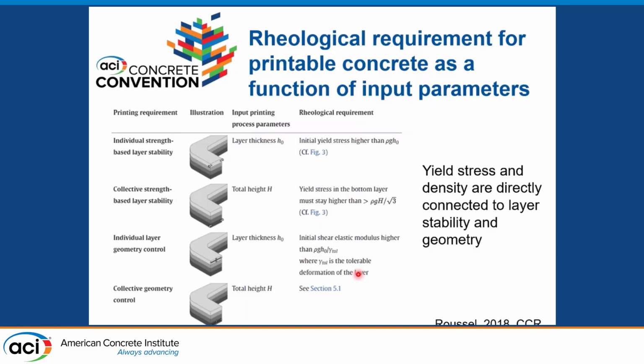But I think the good point is you can also estimate your yield stress with simple tests, like the slump test or the flow table. So that's good to know.